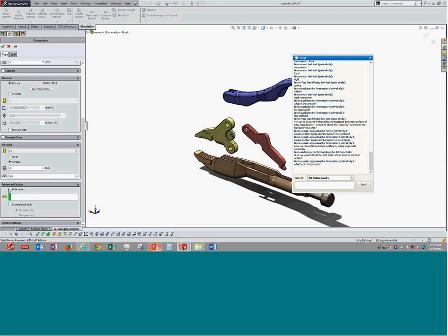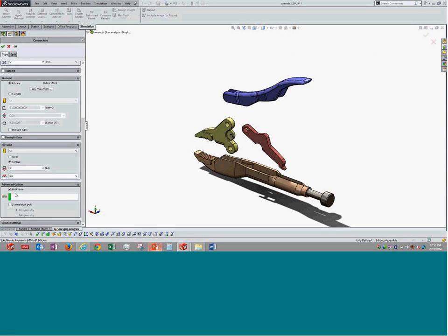It could be a case wherein a huge number of bolts are there, and you might be using only half of them, because of a symmetric condition, you simulated only half the geometry. So in that case you can use this option and tell which surfaces are going to be half. We also have the option of quarter symmetry, so we can use that as well. That can help us in simulating multiple numbers of bolts.